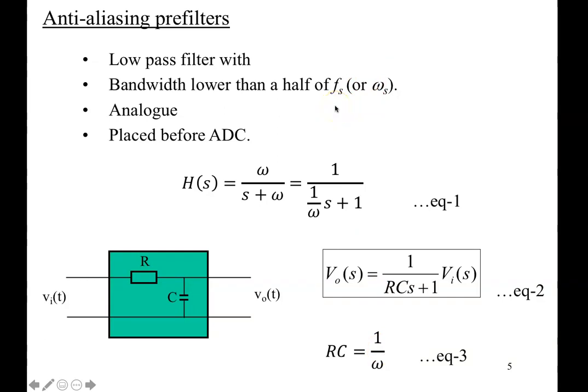Okay, so you choose the sampling frequency to give you a reasonable sampling interval, and you take half of that, and you invert the value. That's the value you should use to design your anti-aliasing filter. It just gets rid of the noise problem, so that computers don't take in these extra signals and treat them as normal low frequency values. Okay, that's called anti-aliasing. Aliasing is a problem where high frequencies get mixed up with low frequency signals because of the sampling process.